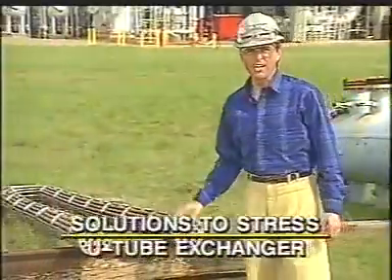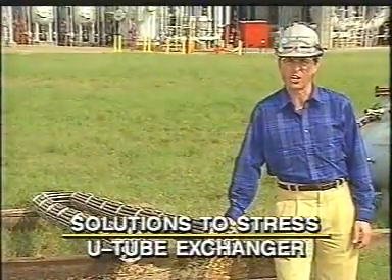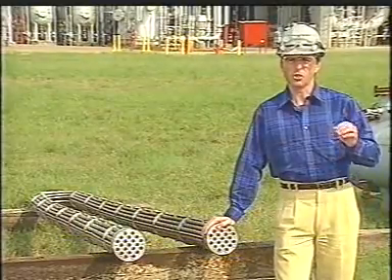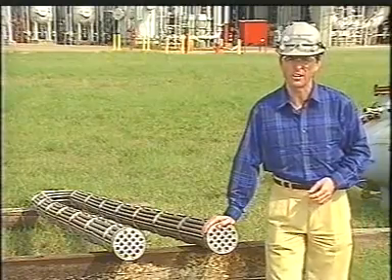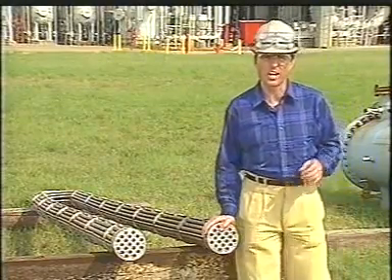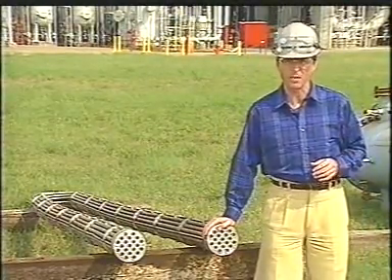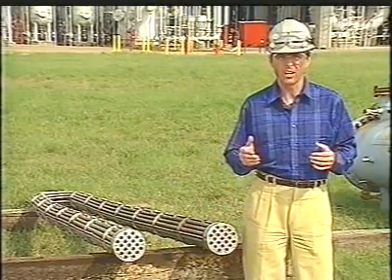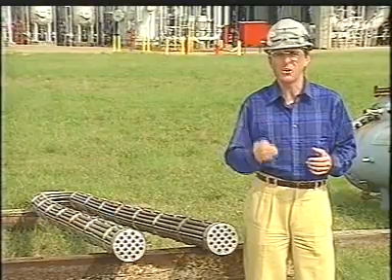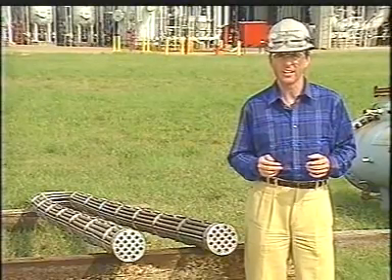The next example is a tube bundle from a U-tube exchanger. In this type, the tubes are free to expand because they're only attached at one end of the tube sheet. So a U-tube exchanger can handle fluids that vary greatly in temperature. Although the U-tube bundle can be removed from the shell, the bends in the tubes hinder internal inspection and cleaning.